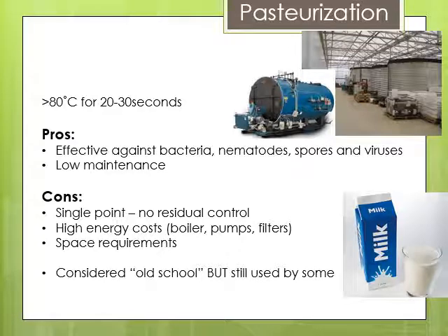This is an interesting thing. It's a single point, no residual control. That means that the water is only treated where it gets heated to 80 degrees Celsius, as opposed to adding a chemical that is persistent in the water as it moves through the entire irrigation system. It has a lasting residual action. Pasteurization does not have that, so that's a downside. Obviously, it uses energy. That's not good. That's going to cost you money.